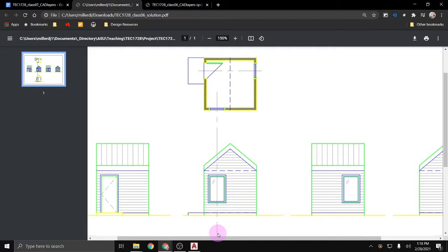So in architectural drawings, we rely really heavily on layers and we color code those layers, because having different line weights in a complicated set of architectural plans, something that isn't a 10 by 10 shack, can be very overbearing. So having different colors is very helpful.